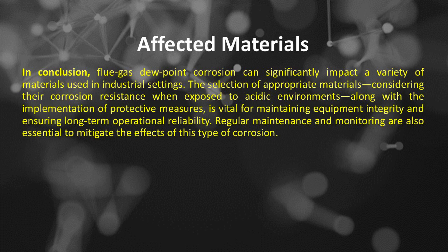In conclusion, flue gas dew point corrosion can significantly impact a variety of materials used in industrial settings. The selection of appropriate materials, considering their corrosion resistance when exposed to acidic environments, along with the implementation of protective measures, is vital for maintaining equipment integrity and ensuring long-term operational reliability. Regular maintenance and monitoring are also essential to mitigate the effects of this type of corrosion.